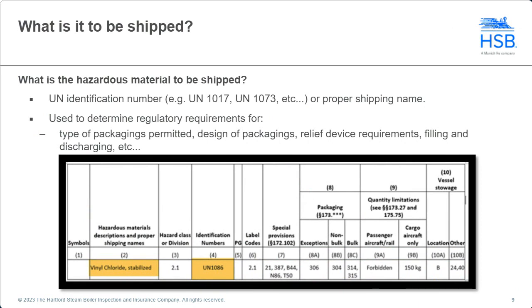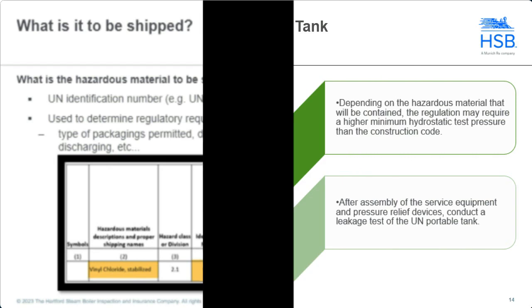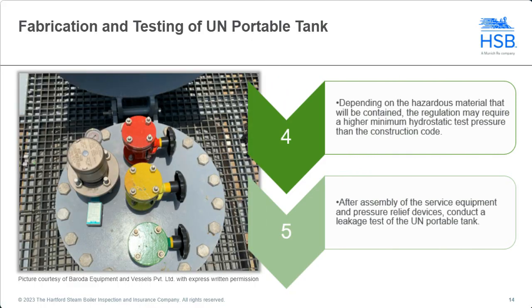This T50 tank is going to have a note, and one of the notes might say minimum hydrostatic test pressure 4 bar, or no bottom openings. So when we go back to this slide, number 4, we want to make sure that we identify those requirements at the design stage, so we don't miss them and we get them captured.